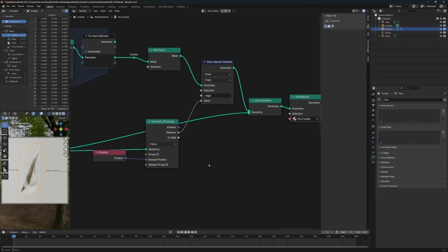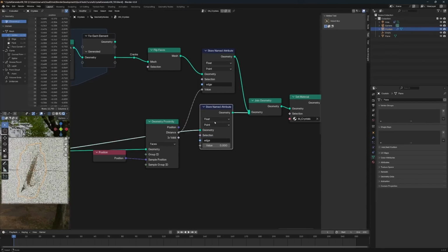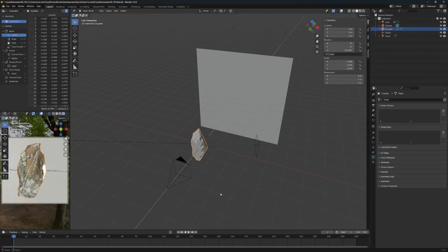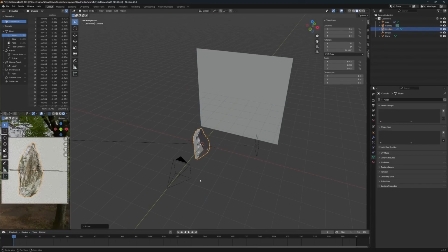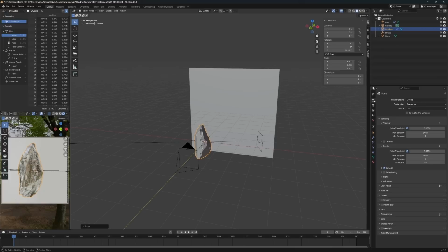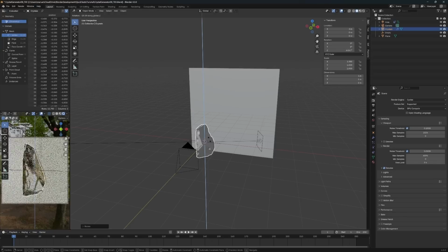And unfortunately it disappears because the edge value is not set. So let's set an edge value on this stream too, set it to 1, and then the outside suddenly appears again, like so. Very good. Now let's see if we rotate the crystal a little bit more, if we can find a more interesting angle, maybe something like this. And of course it's a good idea to switch my renderer to GPU mode, because this will be a little bit faster, like so.